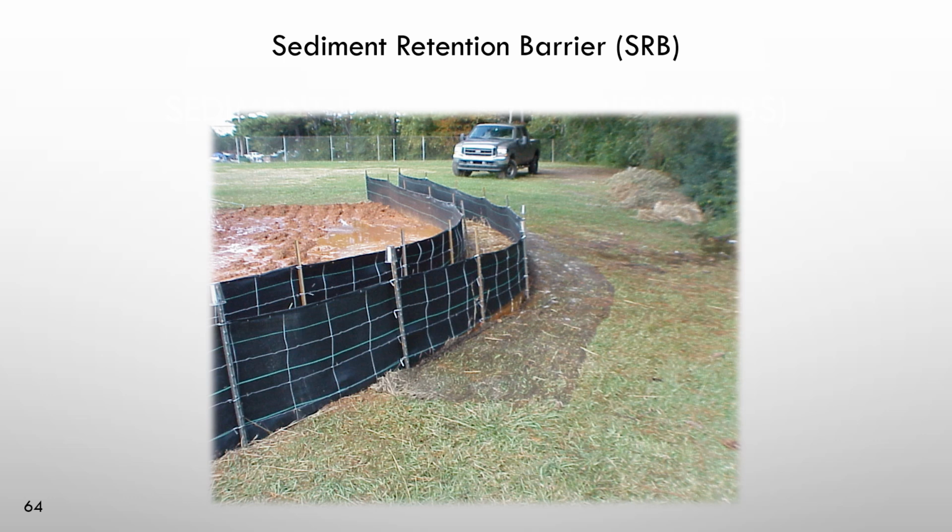of defense. A lot of times we like to use a treatment train system where maybe we'll do some rock checks, some wattles, some polymer enhanced soft armoring. Maybe we have some flock logs leading into a sediment basin if we have them, and then we'll do an SRB as a very last line of defense on the outside. The more polymer enhanced BMPs we can add together in kind of a treatment train system, the better our results are going to be.